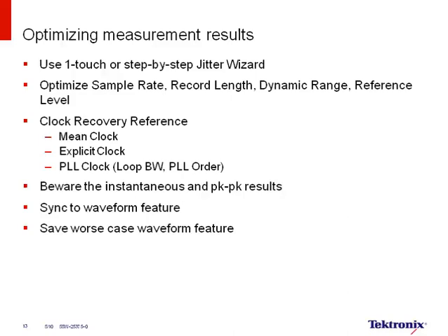But you might also want to add the standard deviation for these measurements is at X. And the reason is your customers can then use the peak-to-peak results, the population, the average, and most importantly, the standard deviation to be able to predict what your system might do.